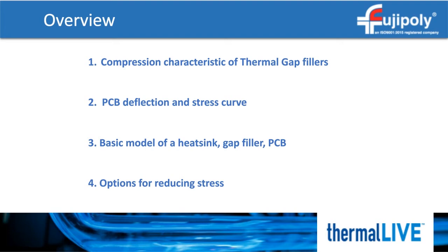The concern with stress is not necessarily with the pad itself. The pad itself will continue to act as a thermal transfer medium, even at higher percent compressions. Rather, the issue is stress and strain in the PCB, and basically what kind of damage can occur if you overstress the PCB. In this webinar, we'll discuss the characteristics of gap fillers and look at how that impacts the PCB. Our webinar is only about 35 minutes, so we won't have time to go too deep in all the concepts, but we hope to give you a better understanding of what exactly is happening when a gap filler is compressed onto a PCB.